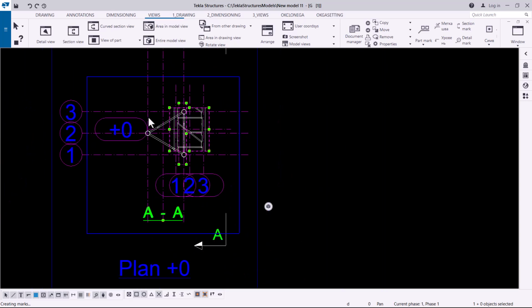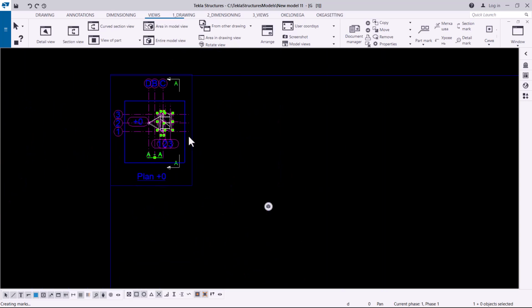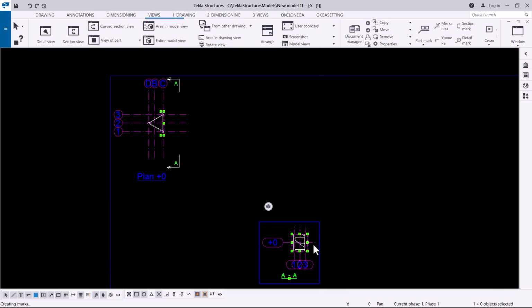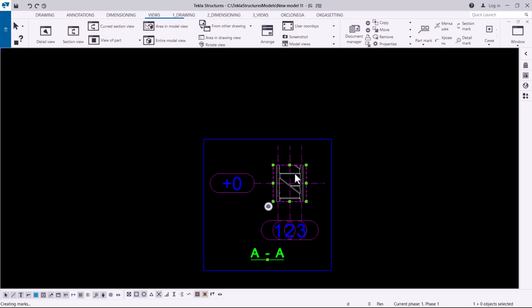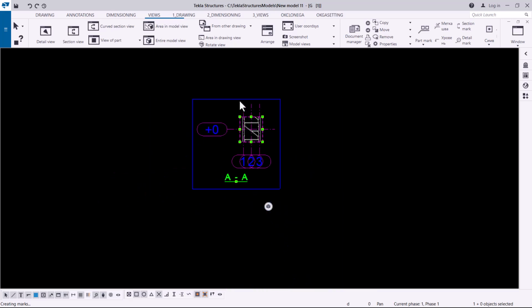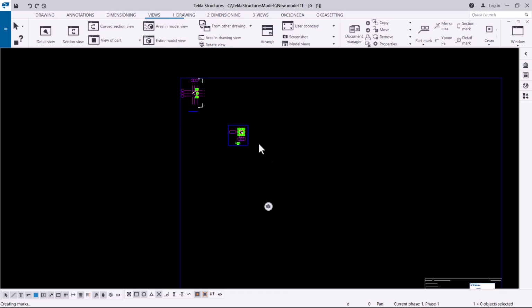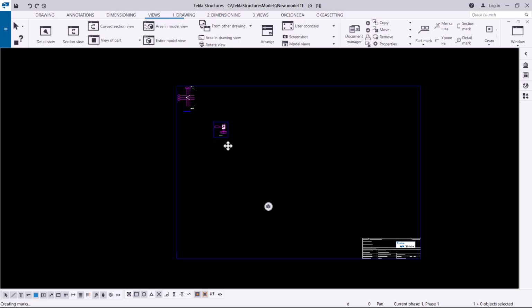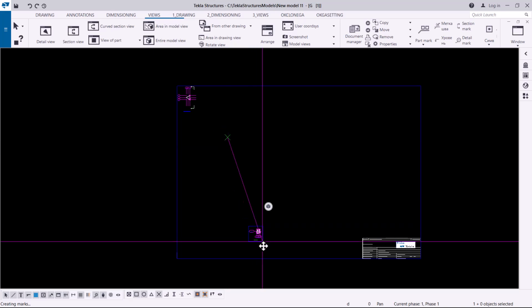The sectional view will be a little bit smaller, dependent on the boundary that envelopes it. But this boundary can be extended to reveal the whole structure or the whole elevation of this particular building. So what I'm going to do, you can see these handles here. These handles are just to help you open up the full height or the full size of the whole elevation. So I'm going to select it. Let me first of all select it and drag it down slowly. Let me just drag it down to this end because it's somehow big,